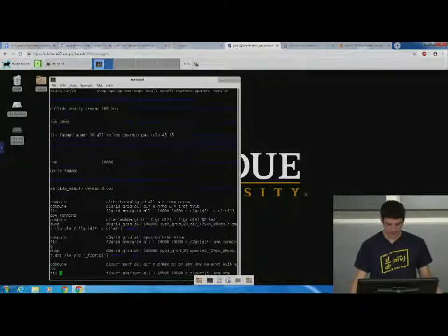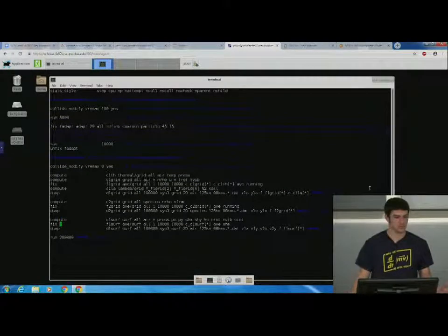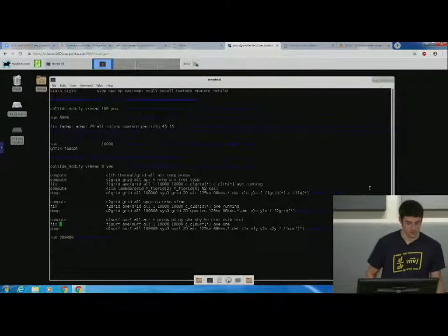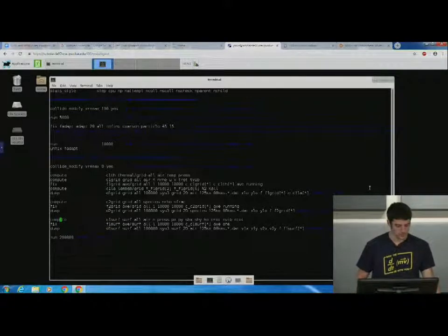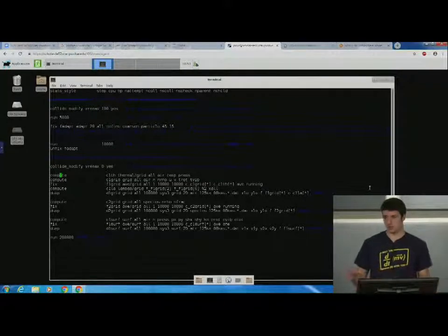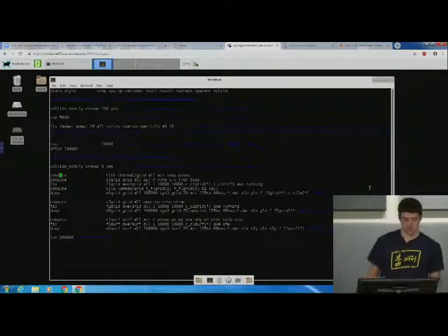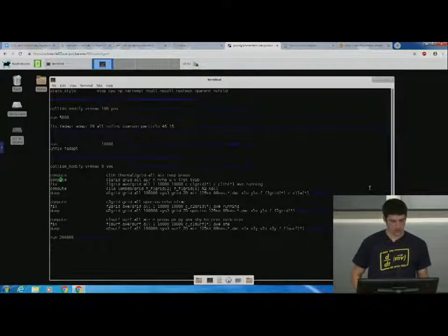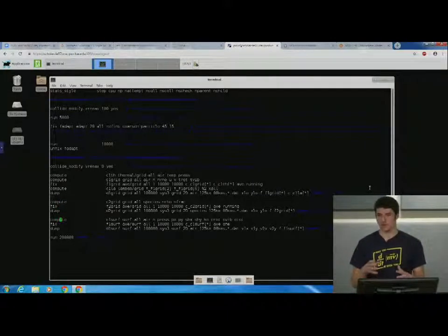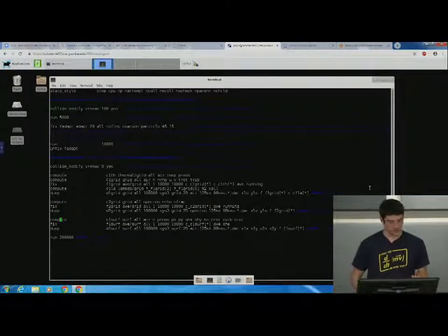And these commands, okay, so these get a bit more complicated, but I guess they're necessary because ultimately you want to see what's going on with your flow, right? So after you run this, you want to see what your results are. There are two things to compute in DSMC for this. You compute your grid properties, so your flow field properties, and that's what makes the nice flow fields to plot and everything. And then you compute the surface properties. So if you're interested in your drag on your vehicle specifically, that's where it comes in.